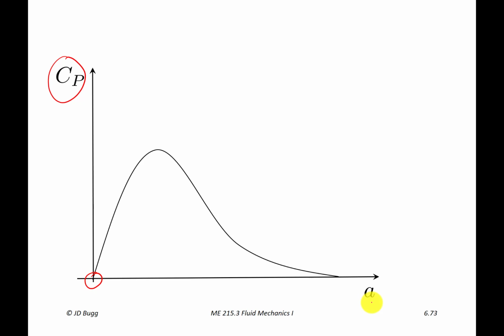Now remember the physical meaning of A. If the axial induction factor is 0, it means V2, the velocity of the wind at the rotor plane, is the same as V1. In other words, it hasn't slowed down at all. And also V4 is the same as V1. So this condition here would happen if the blades essentially didn't extract any power from the wind. Let's say they weren't even turning, or there weren't even blades mounted on it. The wind just blows by, doesn't even notice the thing is there, no change in velocity at all, therefore no power produced. Okay, so that's that limit.